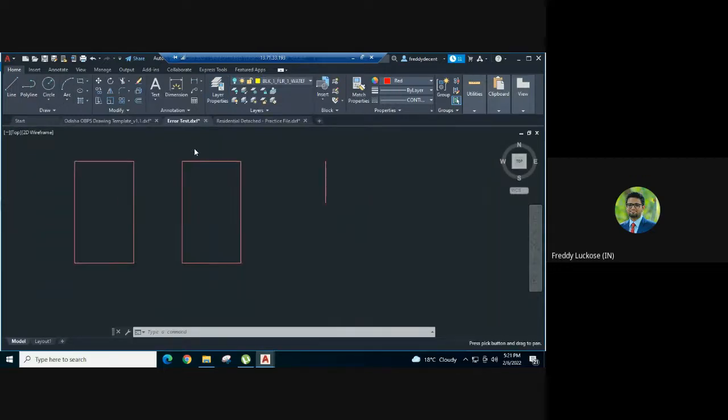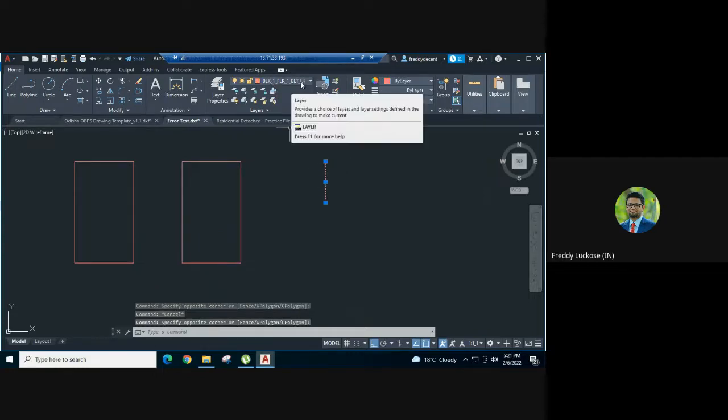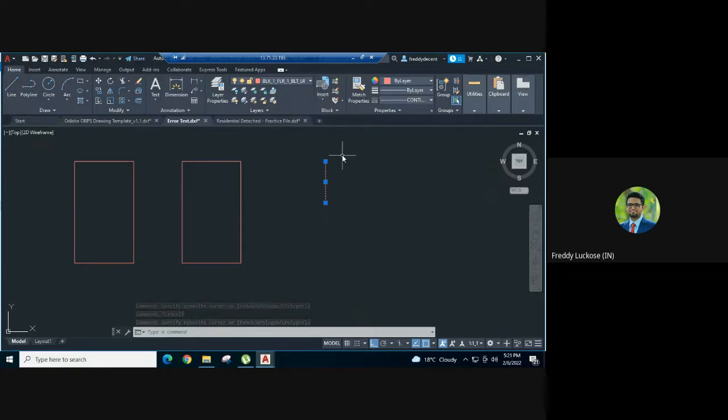The first thing that we see here is that even though we have prepared 2 polygons, by mistake we have made another line and that has the layer name block 1 floor 1 built up area. So this is the reason why the error is coming. On each floor there should be only 1 polygon. There shouldn't be any line or layer that we have created which is not required for the drawing. So we'll just go ahead and delete it.